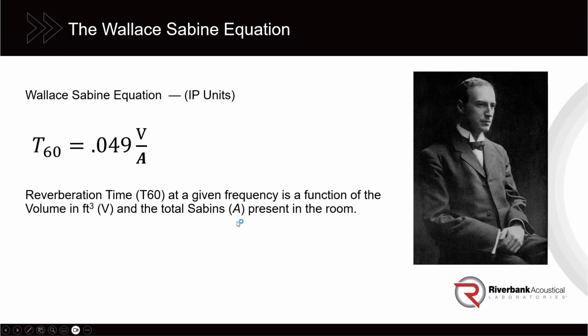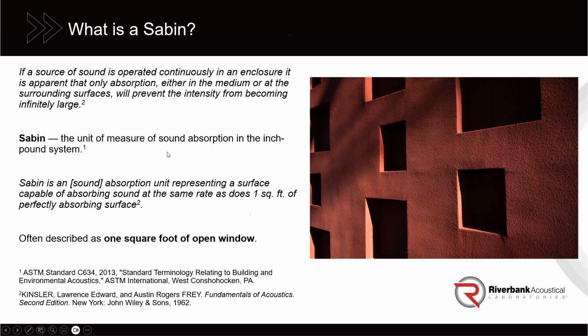Now, in truth, the definition of a Sabin is this item here in the equation. In trying to explain what a Sabin is, the acoustics industry has used different metaphors over time to communicate what we mean. I think one of the originals was that a Sabin is like 1 square foot of open window, or 1 square foot of perfectly absorbing surface.